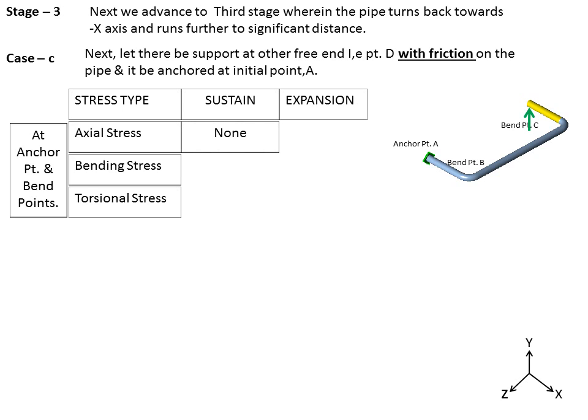Axial stresses, well, none in this case again. Bending stresses remain the same because the frictional force doesn't produce any effect on the sustained stresses. The sustained moments are the same, and therefore we have the same bending stresses in the sustained condition. Torsional stresses again are the same.